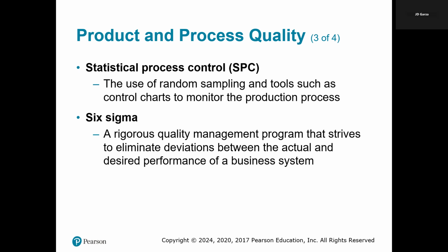Let's just say, for an example, in a pharmaceutical manufacturing plant, SPC might be used to monitor the temperature of a mixing tank. If the temperatures deviate from those set limits on the control chart, production can be paused to prevent the creation of substandard products. As a real world example, Toyota uses SPC extensively in its assembly lines to ensure that parts meet precise specifications, reducing rework and waste.